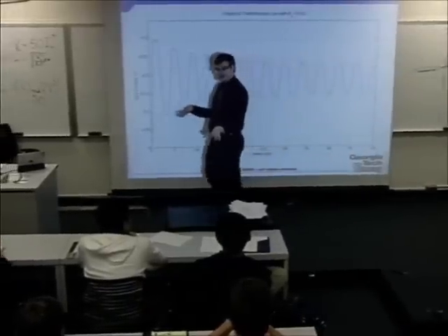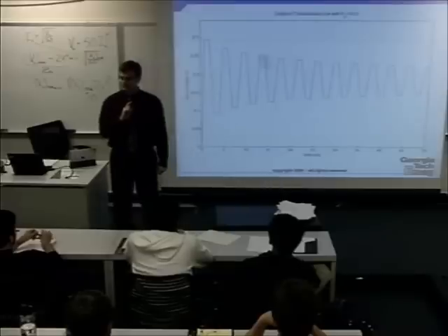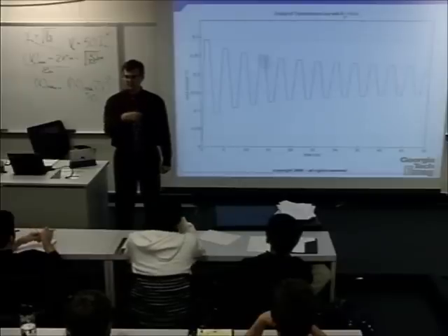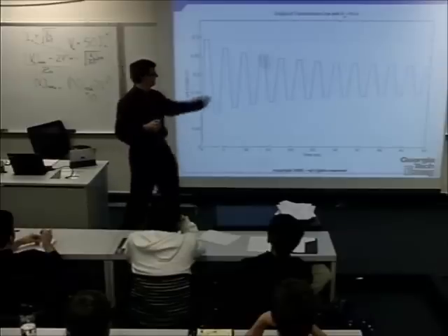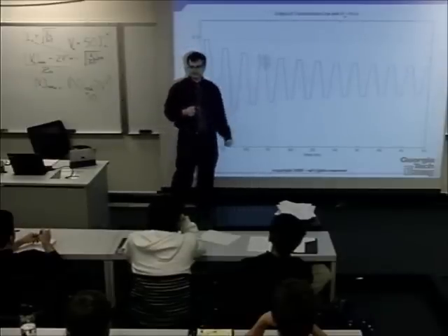In fact, this is a very simple way to make an extraordinarily high-frequency oscillator. What's going to determine the frequency of this oscillator? Simple little circuit. Transmission line, source, tunnel diode. This is 1 nanosecond, the transit time.